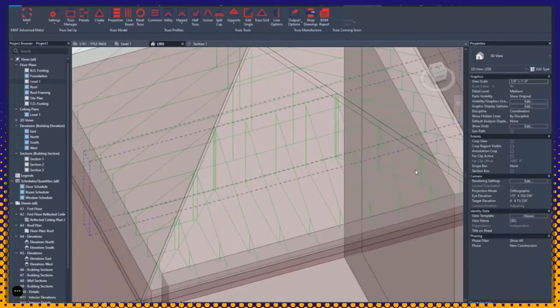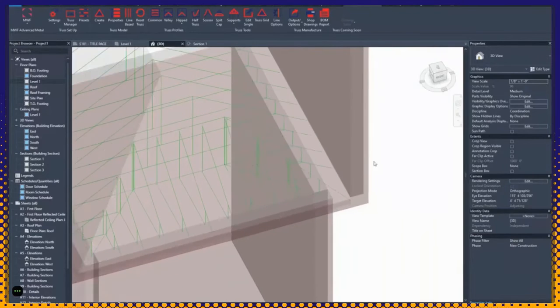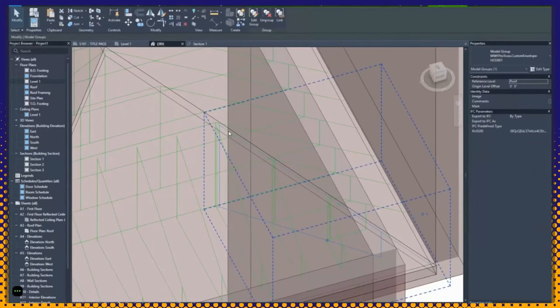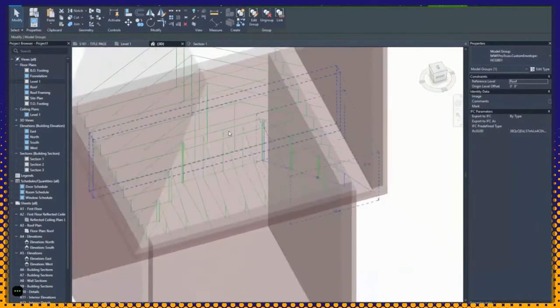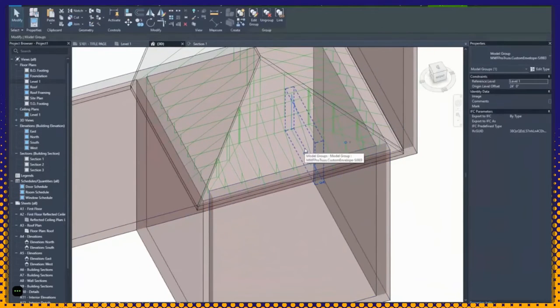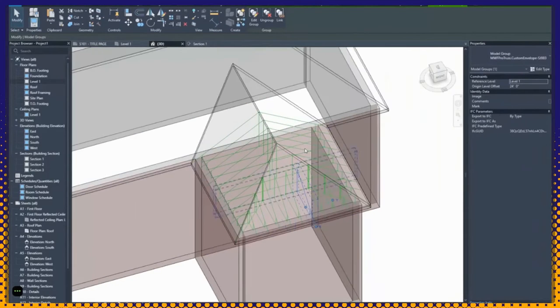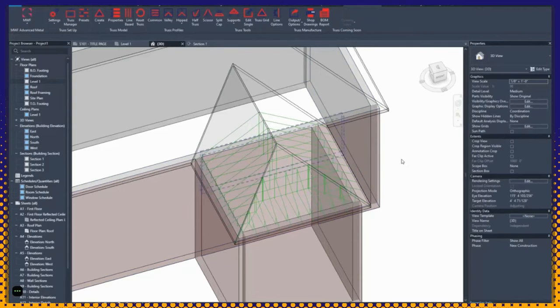And you'll see that it actually created every single aspect of this hip end. So it actually created that diagonal there. It's calling it HCG. And then over here we have another one, which is SJ, so side joist. And you can basically play around with the locations if you like, but just be mindful that since these are at a slope, you will actually need to make sure that your offsets are correct. So if you do make a mistake with any of the girder options or any of the hip end options, just undo and redo the envelope. It's easier than manually modifying the model lines.